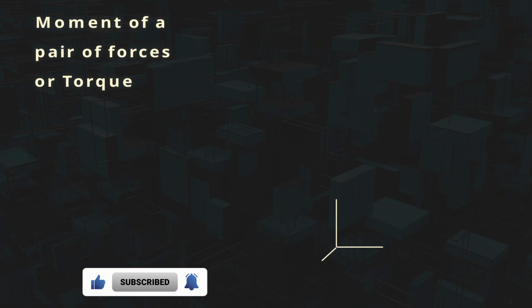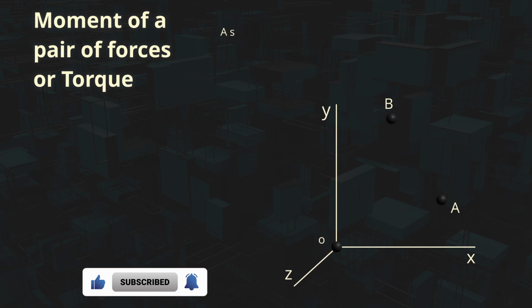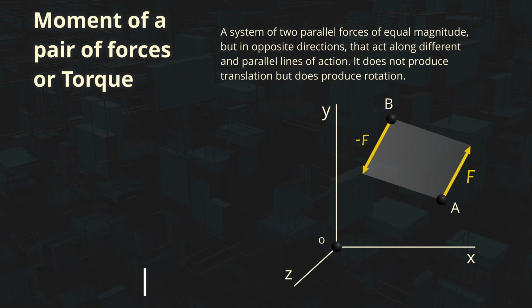A torque is a system of two parallel forces of equal magnitude, but in opposite directions, that act along different and parallel lines of action. The effect of a torque is only rotational, that is, it does not produce a resultant force that can move the rigid body, but it will produce a moment that will tend to rotate the body.